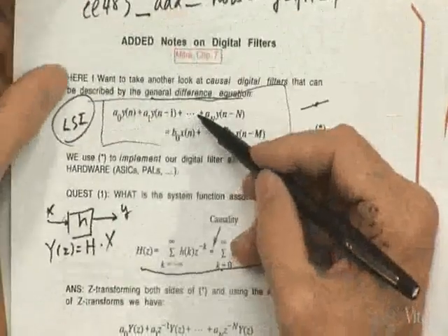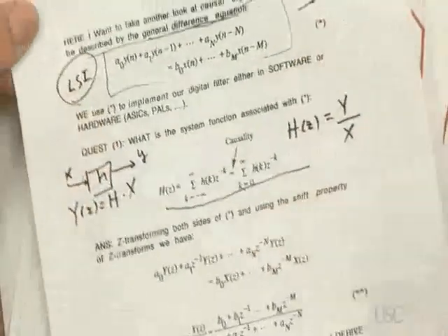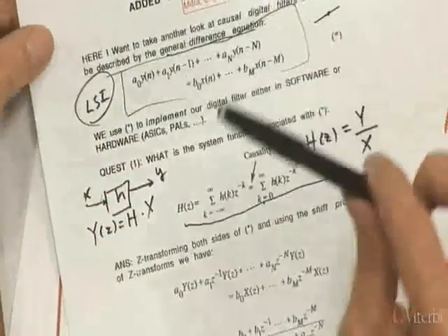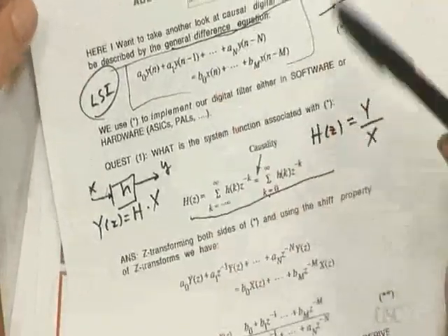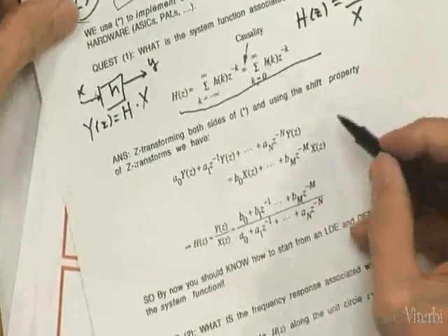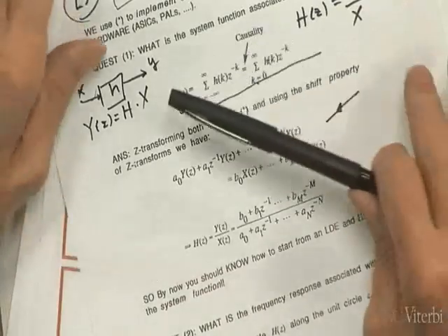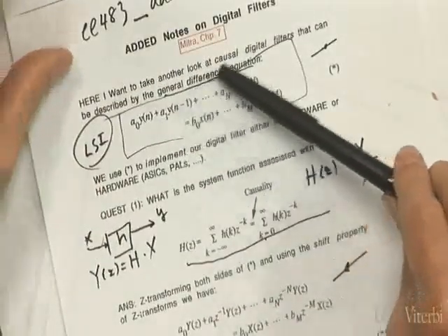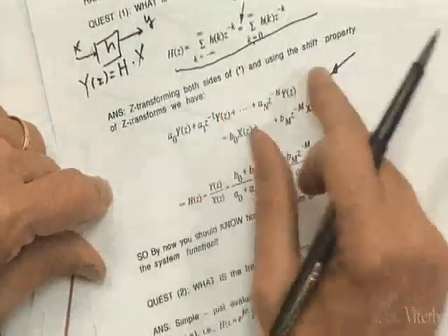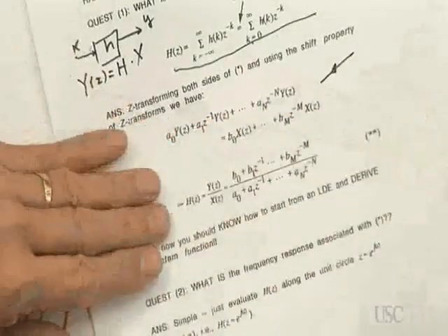So let's take our difference equation. Let's use all the properties of the z transforms that we know and love: linearity, the shift property, and so on. And let's take the z transform of both sides of this difference equation. And when you do that, you get this. And the beauty of it is, in the time domain, you had delayed versions of y. But in the frequency domain, you just have Y of z. All those delays turn out to be powers of z inverse.